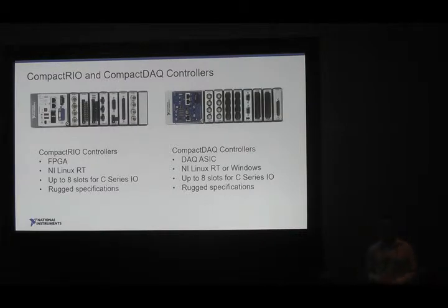Awesome. So just to make sure we're all on the same page, CompactRIO and Compact DAQ controllers in many ways are very similar. Both feature the same rugged specifications. Both have up to 8 slots for C-Series I/O, so a wide breadth of I/O that you can integrate into the product. Both have the same real-time operating systems. Compact DAQ controllers do also have the Windows options.